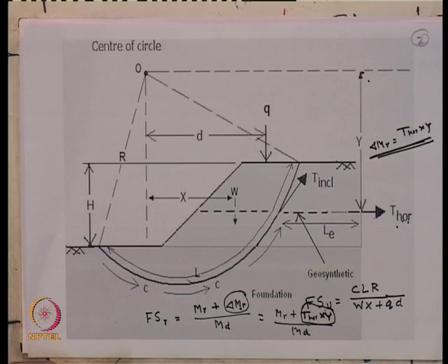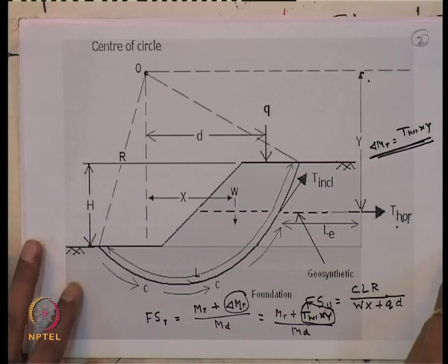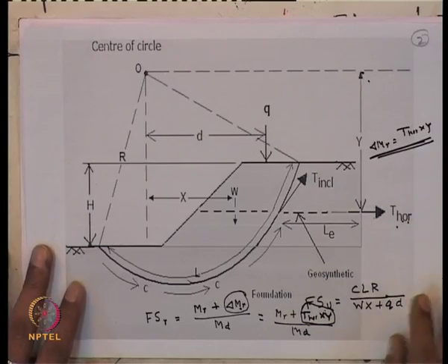If in the unreinforced case the factor of safety is less than 1, then you can introduce the geogrid material. If you place one layer of geogrid between the foundation and embankment and it does not satisfy, you can give 2 layers, 3 layers, 4 layers, and see whether it satisfies the factor of safety. Even then, sometimes for the construction of the embankment, a very high strength geogrid can also help you stabilize the structure.